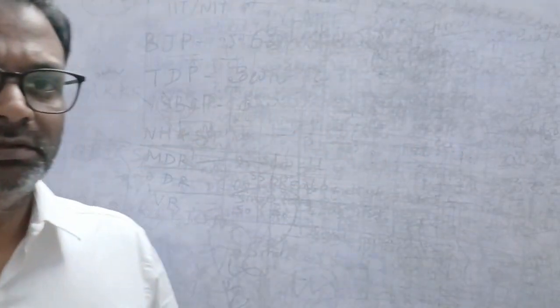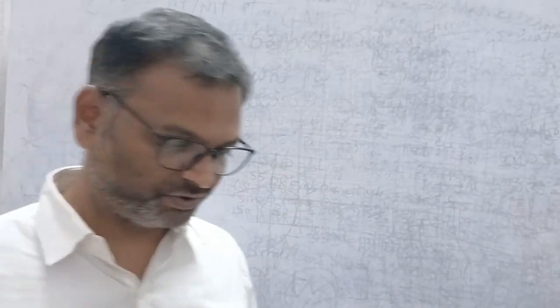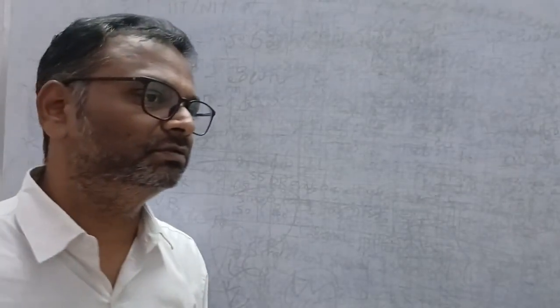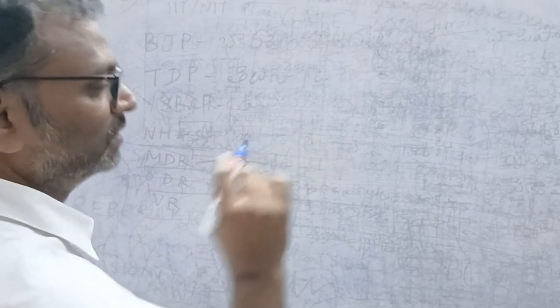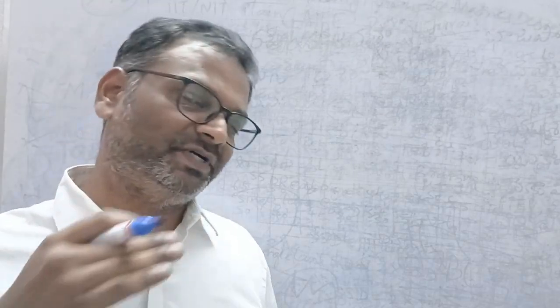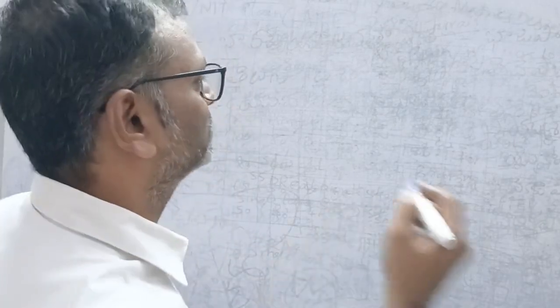During calculating sight distance, if the data is not given regarding design speed or speed of the vehicle, then you have to adopt a design speed depending on the classification of road and classification of the terrain on which the road is located.